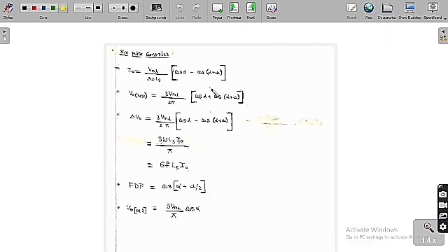Now we have discussed the single pulse converter and 2-pulse converter. So now we are going to study the 6-pulse converter directly, and see what formulas we get with the effect of source inductance. Here I naught is equal to VML by 2 omega Ls into cos alpha minus cos of alpha plus mu, where VML means the peak value of the line voltage, which is root 3 into Vm.